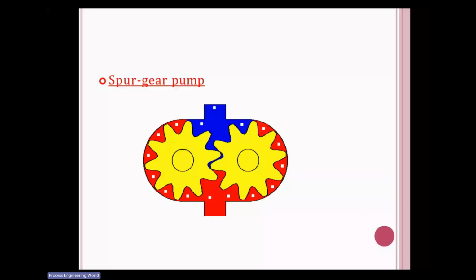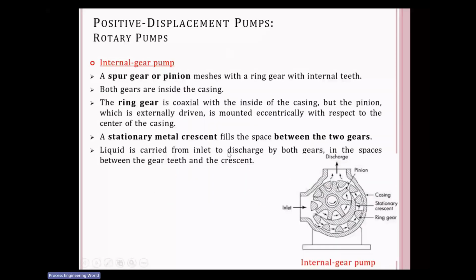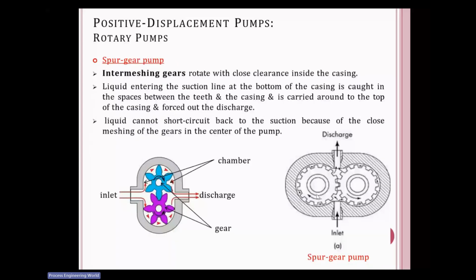Now what we are having is internal gear pumps. You won't have seen these internal gear pumps in any fluid transfer operations, I believe. Its design is quite complicated, which makes it an interesting gear pump. So what actually is the difference in design? You have a crescent moon. In this gear pump, you have a stationary part and you have a rotary part, both. What we saw earlier in gear pumps is that both are rotary parts, both in rotary motion.